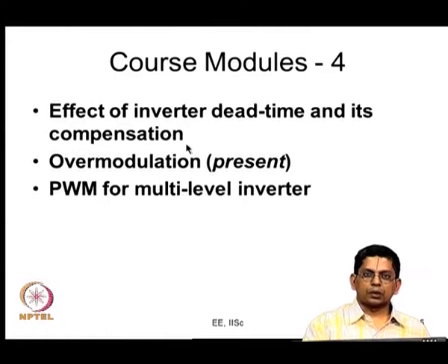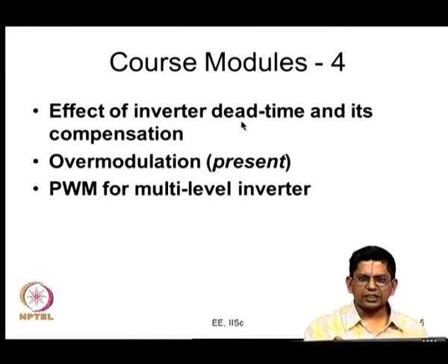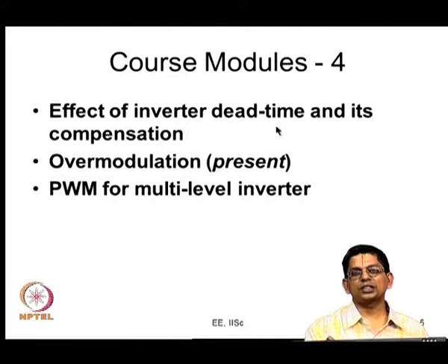So, we could do that. Here we are going to look at something nonlinear. Firstly, what we found was that the fundamental voltage is no longer proportional to the reference, because that is the ideal fundamental voltage. On top of the ideal fundamental voltage, there was a small component getting added, which is the fundamental error voltage caused by dead time, and what you get is the phasorial sum of these two, the ideal fundamental voltage and the error fundamental voltage.